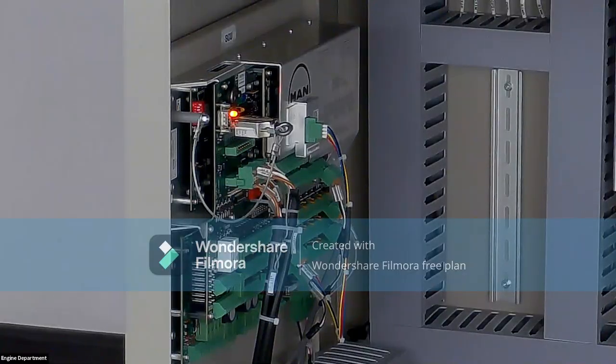After a few seconds of initialization, the orange color turned to a blinking color, two red, one green. And if we check the presentation on the LED information code, two red, one green means application download in progress, scanning for server. Now the LED code indicates two red, two green, which means application download in progress, downloading program. So the software is downloading.